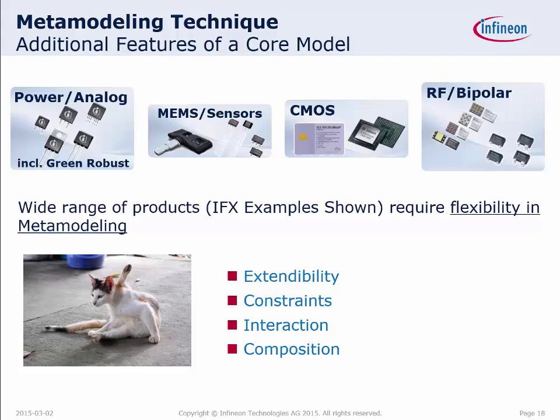That means it's almost impossible to have one generator covering all the needs of Infineon. It starts with firmware header files. If you have a different CPU architecture, you need different firmware header files. I've seen already 10 different firmware header file generators and styles to fit the needs of the specific projects.